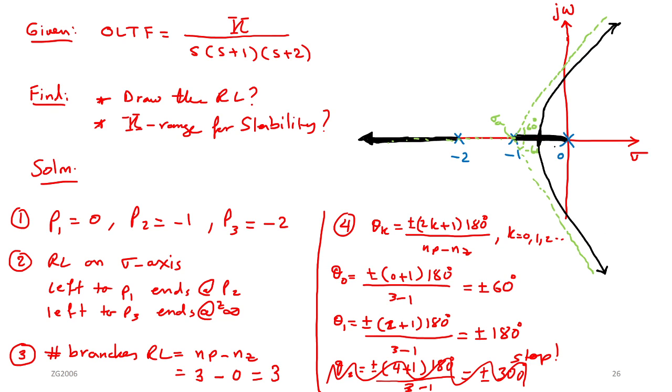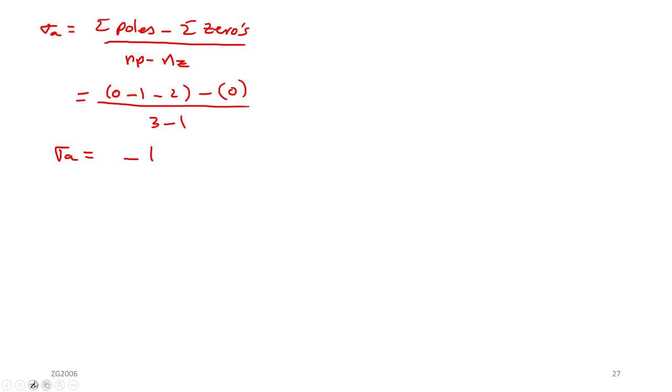So you can see the root locus is always symmetrical. The real axis is always like a mirror. What you see in the top, you will see in the bottom. Why? Because if you have a root of the characteristic equation and it's a complex number, then its complex conjugate is also another root, right? You see? All right. So let me write what I did here.